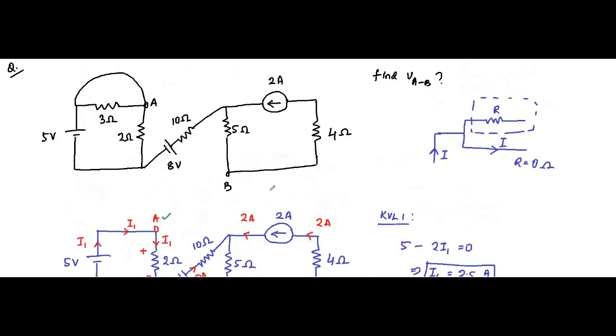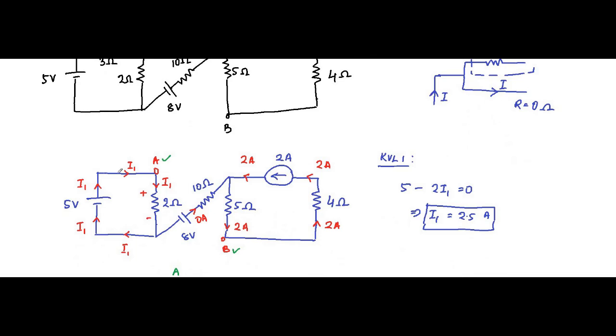Okay, so again, with a basic understanding of the behavior of circuits along with KVL and KCL application, we solve the circuit. The first concept we used when we approached the question is that current always takes the minimum resistance path. That's why this 3 ohm resistor went out of the circuit. We replaced it with a short circuited path.